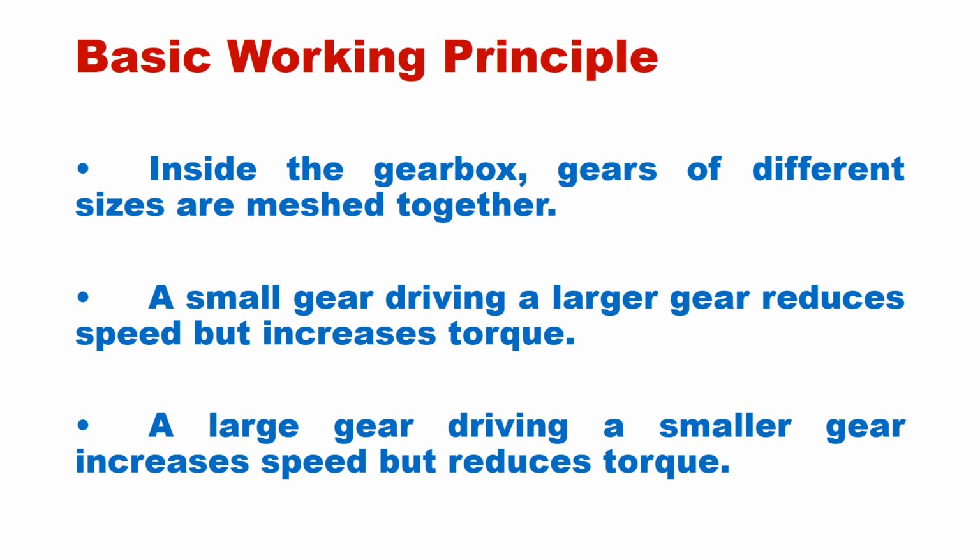Basic working principle: inside the gearbox, gears of different sizes are meshed together. A smaller gear driving a larger gear reduces the speed but increases the torque, and also a large gear driving a smaller gear wheel increases the speed but reduces the torque. It is the basic principle of the gear.